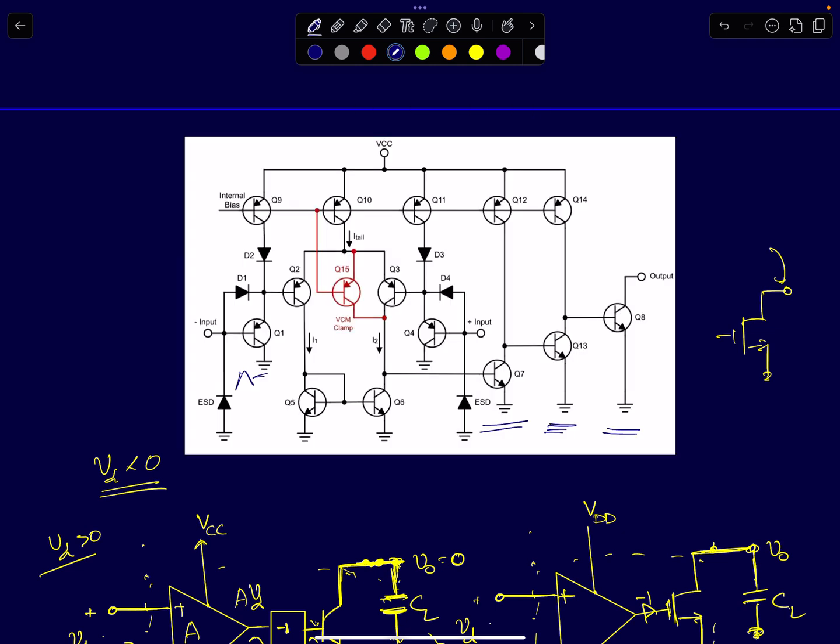I've already shown the different amplification stages. We already said that a comparator is a voltage amplifier with a very high gain, like an op-amp. It doesn't have any compensation capacitor because it's always going to operate in open loop, so we don't have to worry about stability. In its construction, it's very simple: you just keep cascading as many gain stages as possible to get as high a gain as possible. So that's what a comparator is fundamentally.